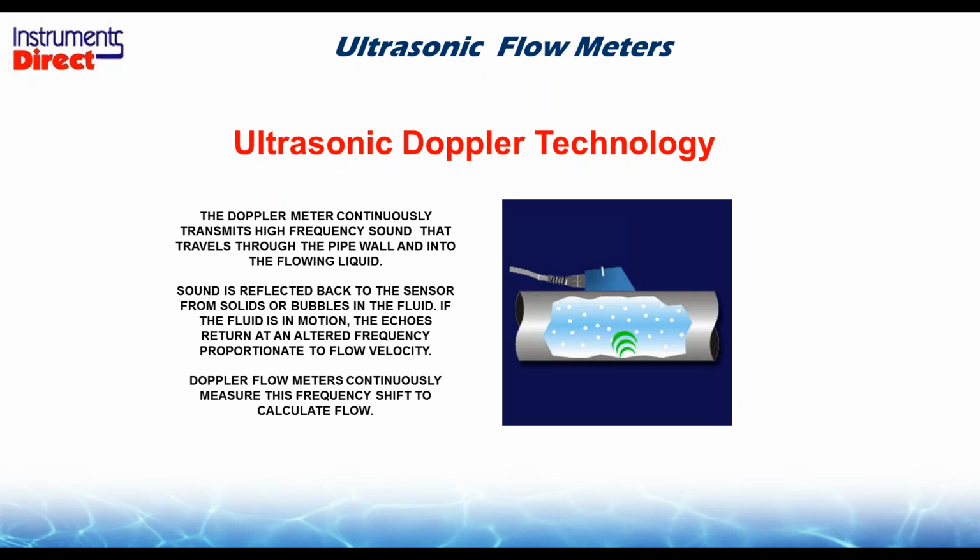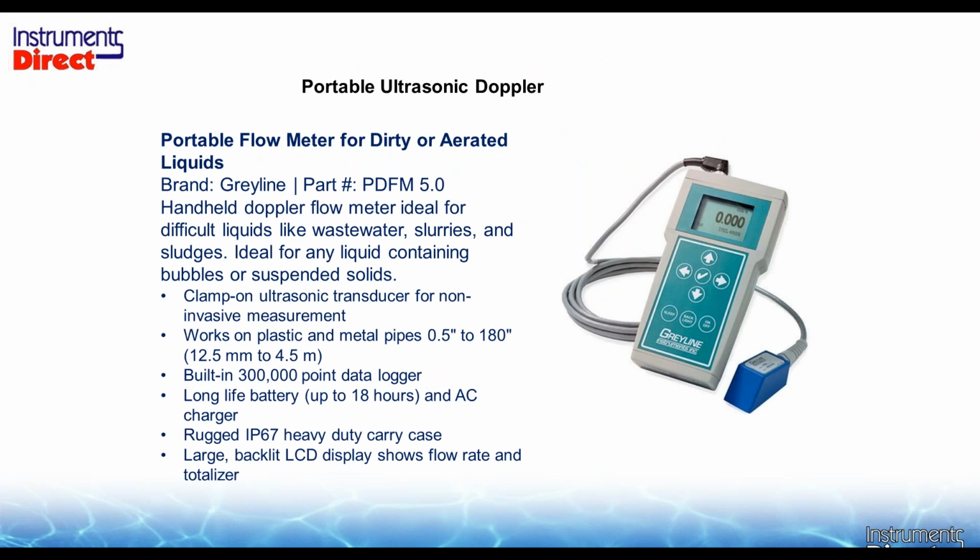So the Doppler is relegated traditionally to the wastewater industry, and you'll find it in some surge applications and typically in a lift station application with shorter runs of pipe, and then the plant itself with the heavy level of solids, and of course the sludge effluents and things like that. So that's the Doppler flow meter, and there are different tools to monitor it.